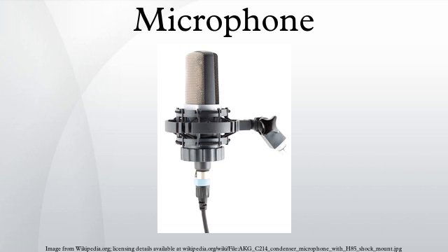The output of a given microphone delivers the same power whether it is low or high impedance. If a microphone is made in high and low impedance versions, the high impedance version has a higher output voltage for a given sound pressure input, and is suitable for use with vacuum tube guitar amplifiers, for instance, which have a high input impedance and require a relatively high signal input voltage to overcome the tube's inherent noise.